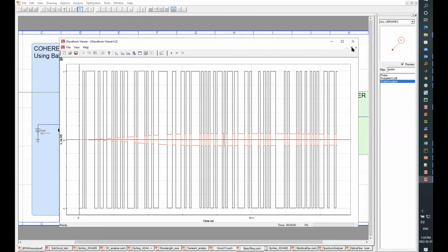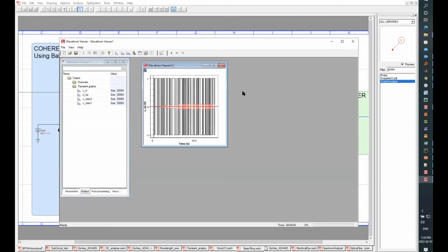The Q is supposed to be mostly 0, but because there's a slight shift in the phase, the carrier frequencies are locked, but by the time you lock the frequencies, there could also be a difference in phase. So that's what we're seeing. There's a bit of a leftover phase difference, but the frequencies are for sure locked. So we don't see the rotation anymore.